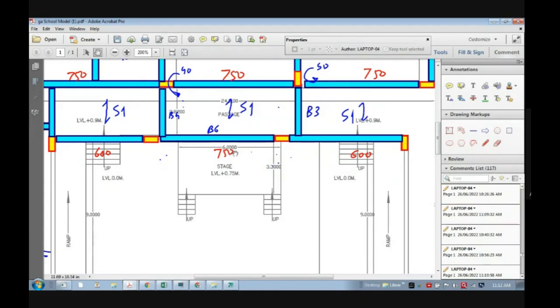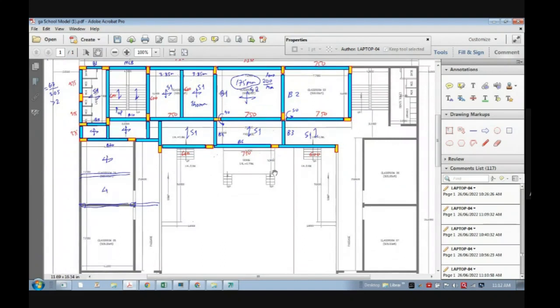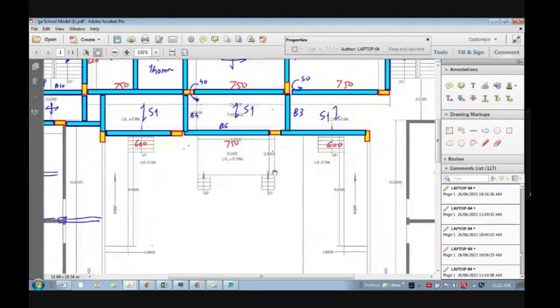So do you think it is a really good choice keeping different beam depth here? So one is the thumb rule, what we discussed, and second is the aesthetic part. Many times what happens, if there is an elevational issue, then you need to keep the beam depth same. अभी यहाँ बताओ, यहाँ you know that whenever you see from this side, whenever you enter the school, you will see these beams. And if you have the beams depth different, then it will not look good.